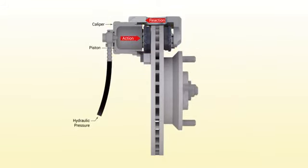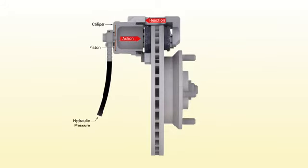The most common type of disc brake is the floating caliper design. When the brakes are applied, brake fluid exerts pressure against the back of the caliper piston. This causes the piston to move out of its bore. This force is applied against the inner brake pad. Because the caliper floats on its mounting hardware, the outward movement of the piston forces the caliper body backward, which squeezes the outer pad against the brake rotor. The clamping action of the pads against the rotor creates a lot of friction and heat. The friction slows the rotation of the rotor, wheel, and tire, and the heat is dissipated into the air.